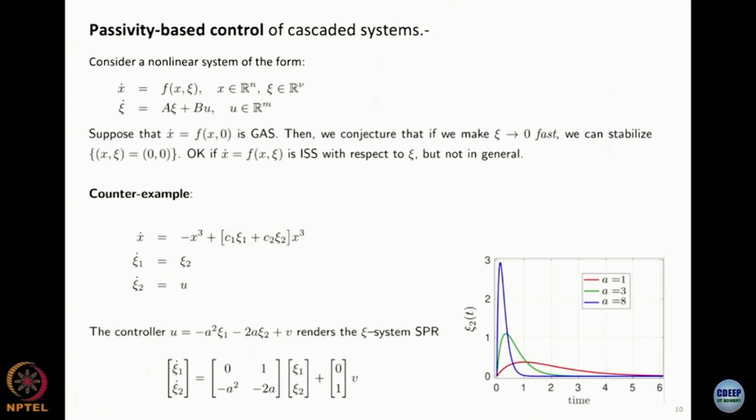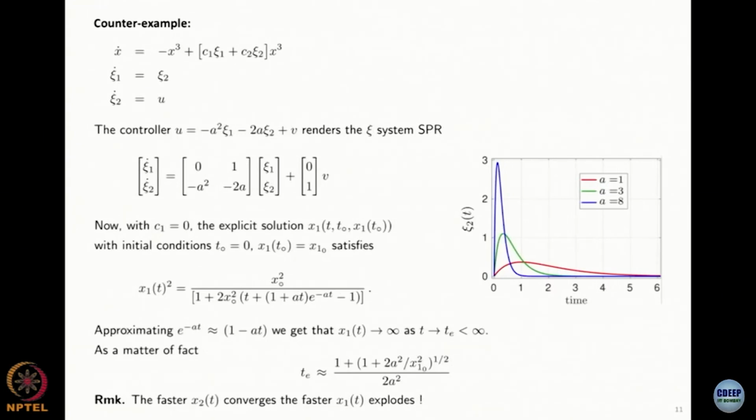So they remark that no, it's not like that in a nonlinear system, because if you say I'm going to stabilize it really fast, well, really fast for this system may also mean that you have a peaking in the transient, you have a huge peak, and then you stabilize it in 1 second. The psi is already very small, but this peak goes to certain levels, and if you inject more and more damping to stabilize it faster and faster, what you will end up with is that your system essentially will explode.